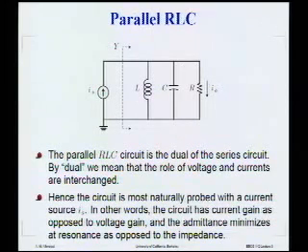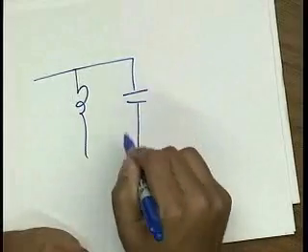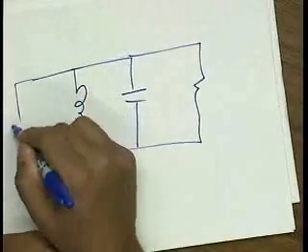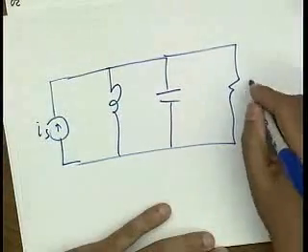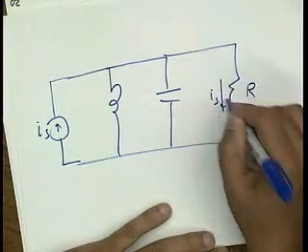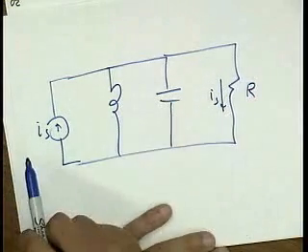Okay, so what's neat in this circuit is just like in the series RLC circuit where we had voltage multiplication, here we're going to have current multiplication. In other words, if we look at resonance, we find that the current in these branches is actually not zero. Let me draw a picture here. So at resonance, I find that IS, all of it, flows across R because these admittances cancel each other out.